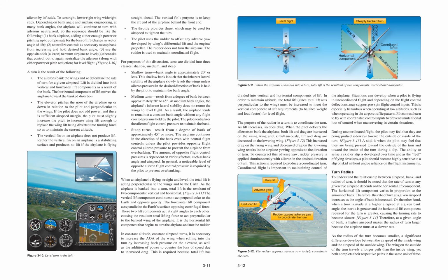A skid is when the pilot may feel that they are being pressed toward the outside of the turn, and toward the inside of the turn during a slip. The ability to sense a skid or slip is developed over time, and as the feel of flying develops, a pilot should become highly sensitive to a slip or skid without undue reliance on the flight instruments. Turn radius. To understand the relationship between airspeed, bank, and radius of turn, it should be noted that the rate of turn at any given true airspeed depends on the horizontal lift component.